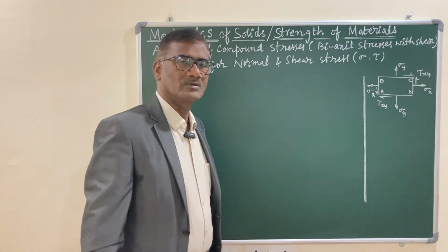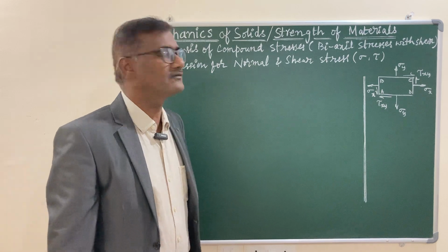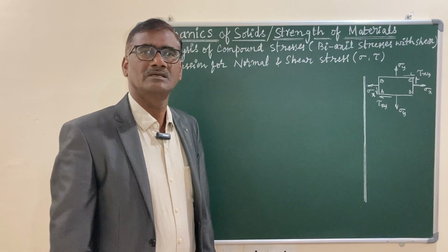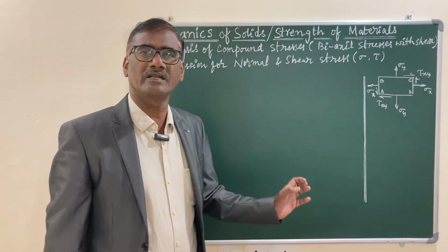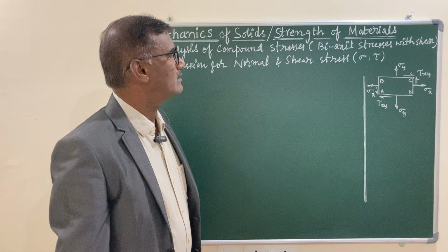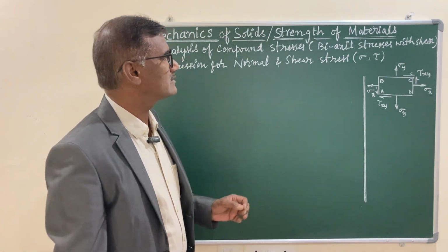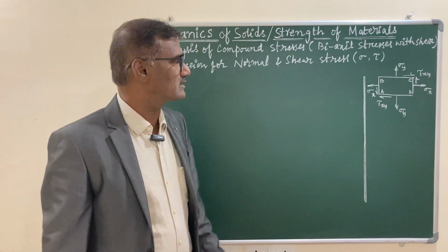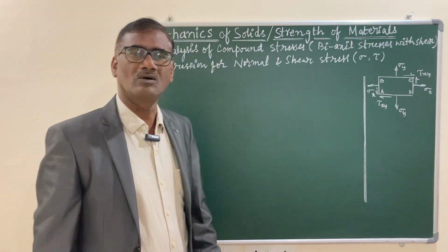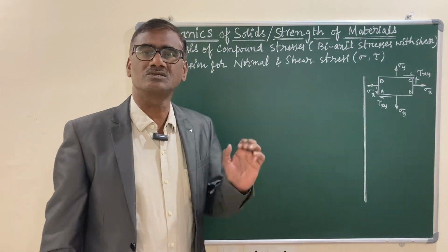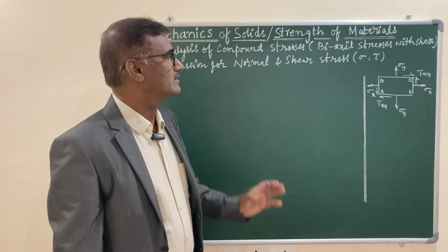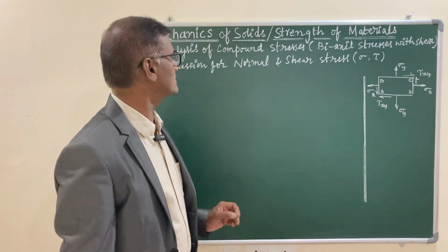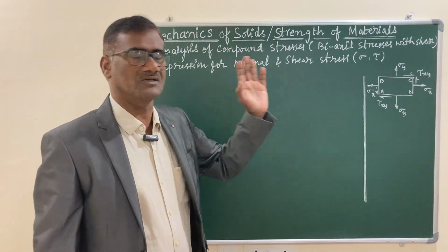This is a more practical approach, as you know, in fundamentals of strength of materials, that is in first unit of your syllabus, simple stresses, which is an idealistic approach. Usually you will come across a body subjected to biaxial stresses, or compound stresses, and your intention is to calculate in which direction the maximum stress is possible. With that intention, you are going to derive the expression for the normal as well as shear stress.